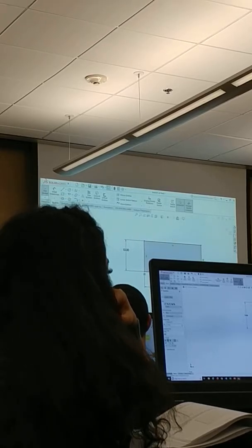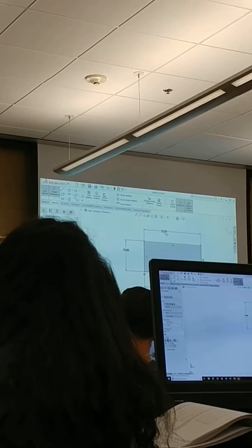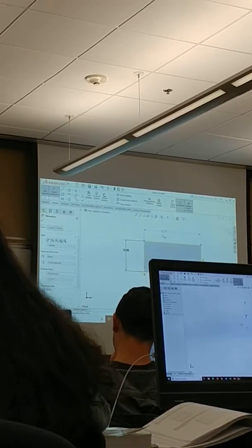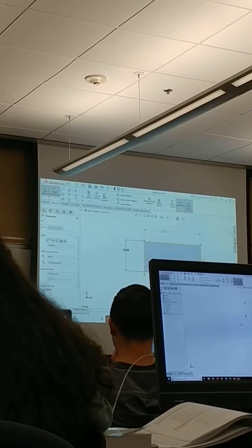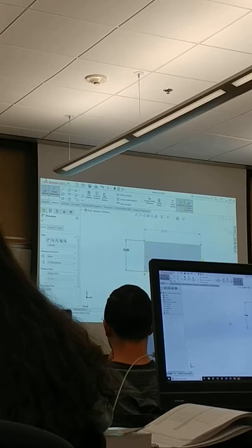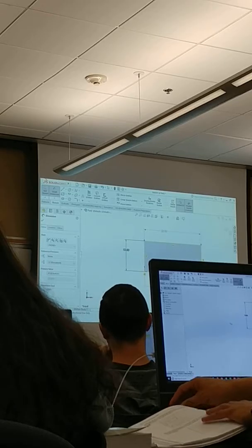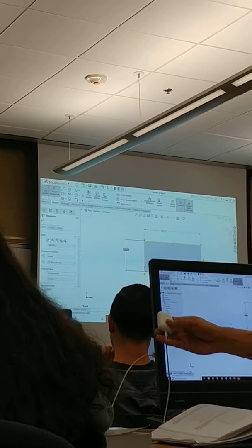The other thing is if I pick the other option and say I'm going to make it the driving dimension, I'm going to start getting a whole bunch of errors. Basically they're in conflict now. This one's in conflict with this one. So now you're seeing all these colors. It says in the bottom right corner, if it's yellow, it says items are in conflict. And if they turn red, then you've got a real problem, and that will happen. That means the item is unresolvable. It cannot figure itself out. So right away, when I start seeing stuff like this and all these little pictures, there's a problem. It says overdefined. You see it in red right here.